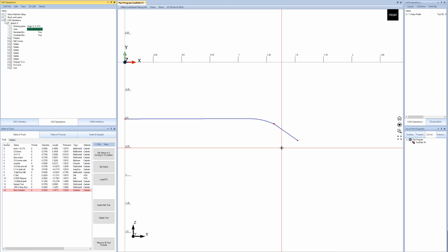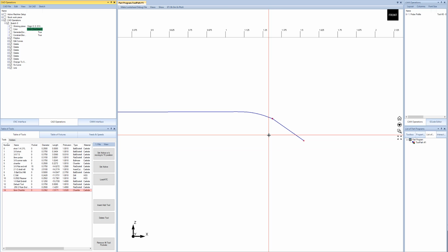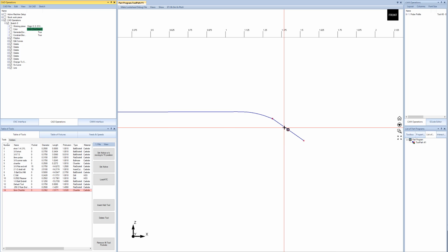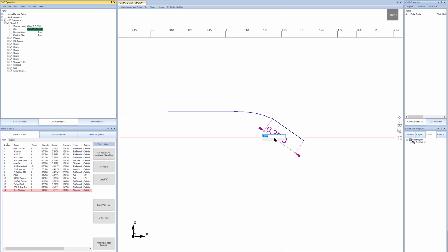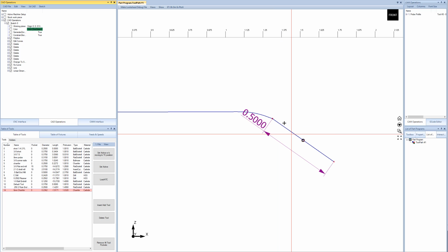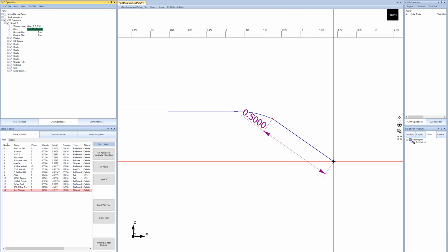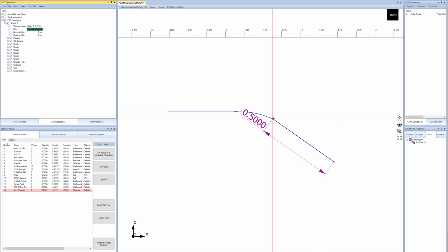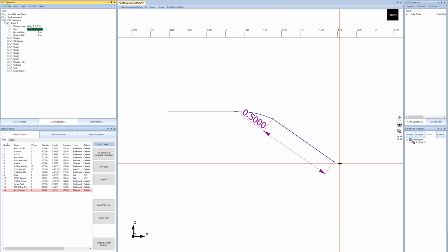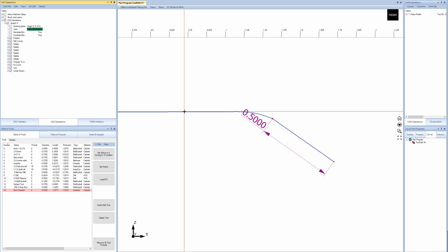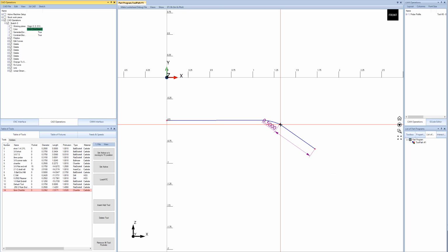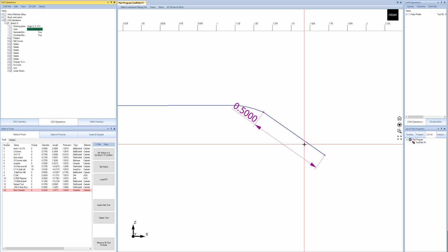So that's great. Now I'll hit D on the keyboard for dimension, and then just click on that new line, and I'll give it a dimension. This is basically just a length. So I'll change it from whatever we had drawn before to 0.5. Now you can see that the only point that moved was this one, because these points are coincident, so it determined that this point has to stay fixed, and it can only move this side. Had we not fixed this curve down, it may have tried to move this point instead. So that's why we did some of those things earlier.